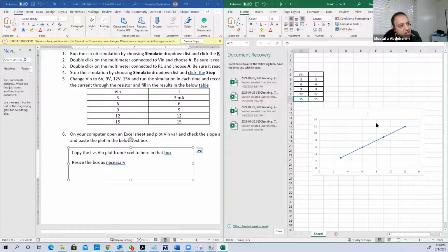In linear relations, we need just 2 points, but we made 5 here, although 2 are enough, I can say. But for nonlinear devices like diodes, you must have many points to test: change the voltage, and test the current each time for many values.